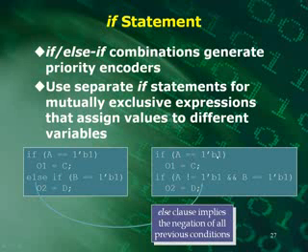You should just say if A equals 1, output equals C, because that's what we want. And in this case, because we did an else if B equals 1'b1, what we're really wanting here is if A is equal to 0 and B is equal to 1, then we want output 2 equal to D. So we should write these as two separate if statements. So try not to be doing this type of thing when you write your if statements. And do them like that. Do them separately.